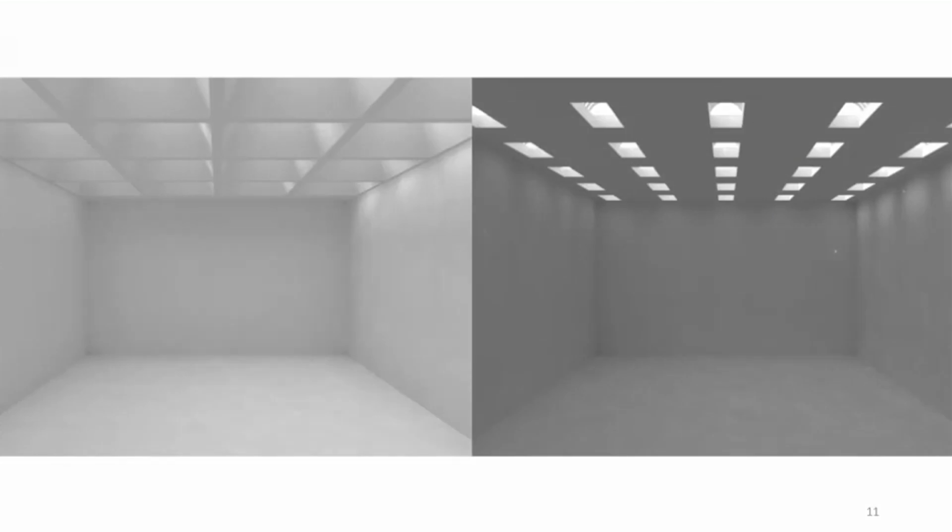And the third principle was really looking at the ceiling design and how to optimize the lighting performance by both minimizing the horizontal ceiling and increasing the light through design. So this one's really interesting. The image shown here, and I'll come back to this a little bit later, the skylights are actually, we have an equal amount of glazing. So the glass area on both of these images is the same. It's just the ceiling design is different, and you can see the brightness difference. So I'm going to come back to that concept a little bit later.